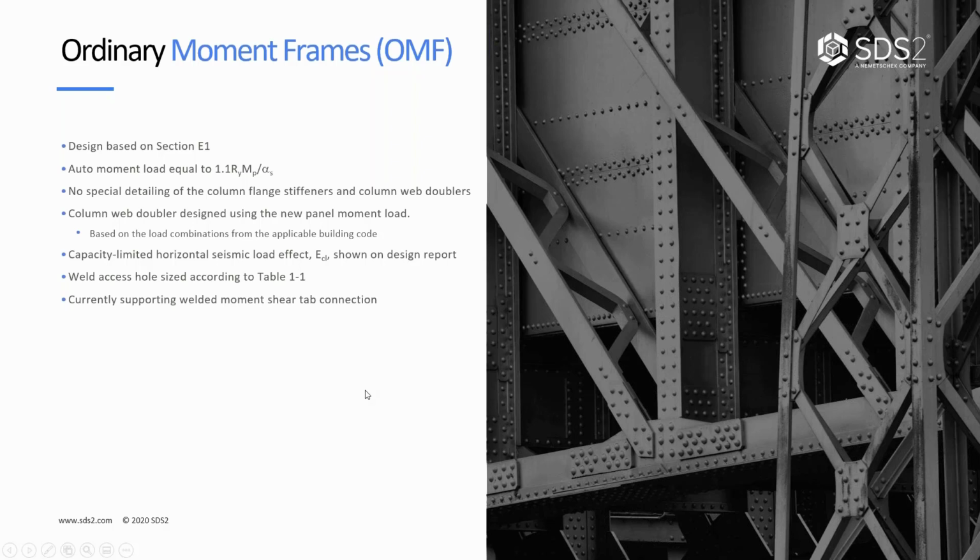We do continue to do the weld access holes according to table 1-1 of the seismic manual. And currently, the only connection we've had time to make sure we have a fully supported design for is the moment shear tab connection.